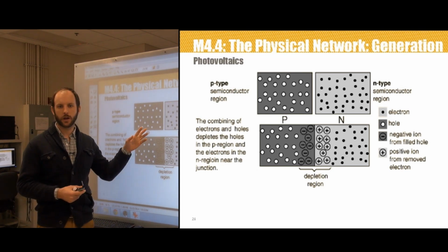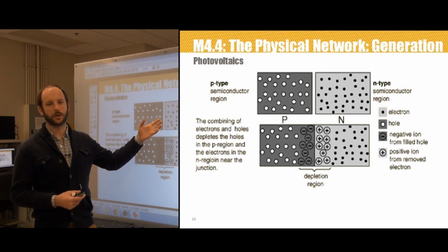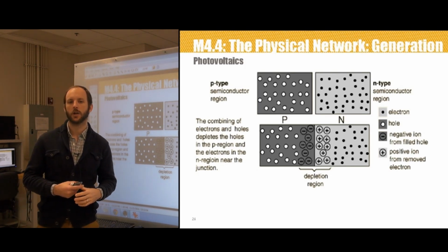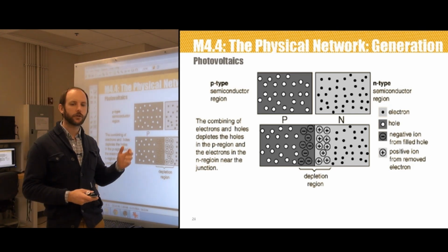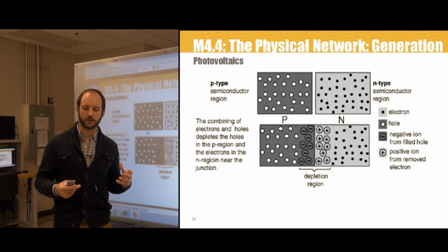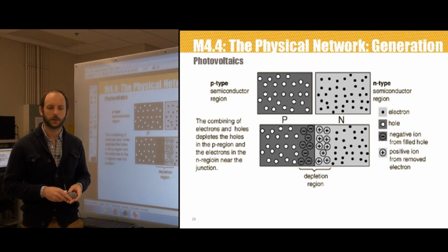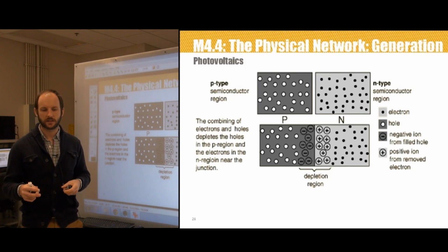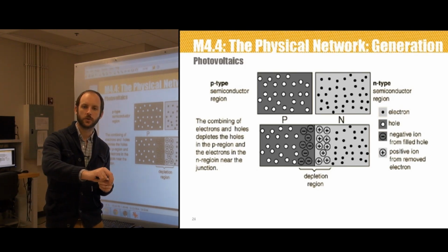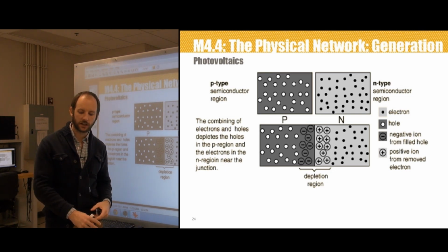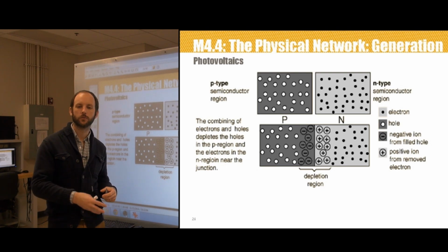It's a little different phenomenon. The motion of holes occurs because electrons can fill holes, but when they do, they must leave a vacancy in the crystal structure, creating a new hole, and therefore net motion of the hole. When I first learned about this, the example of students in a classroom with an empty desk was used for me. Say there is one desk that is empty, and a student chooses to move to that new desk. Well, that vacated the desk that the student was in, and now another student can be free to move to